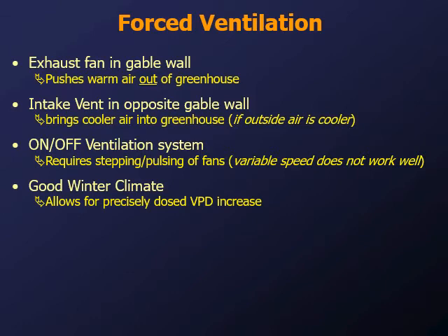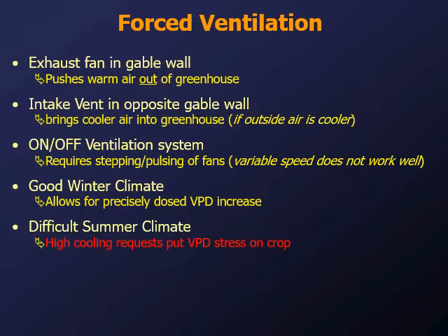In the winter, this is excellent because it allows us to just turn on 1 or 2 fans to bring in fresh air. Remember, we're always concerned in the winter that we're going to end up with too little vapor pressure deficit, which means very high humidity. So by venting air out of the greenhouse and bringing drier, fresh air in, we can maintain a suitable humidity for the crop so that they can actually transpire. So fans are often seen, especially in ornamental greenhouses, in combination with natural venting to make sure that in the winter months they don't end up with a poor environment.